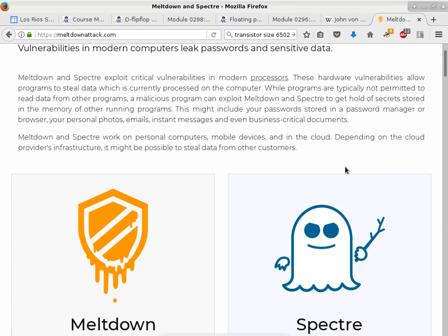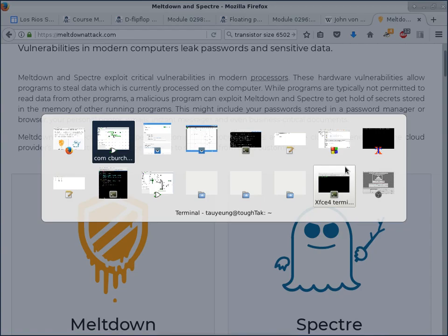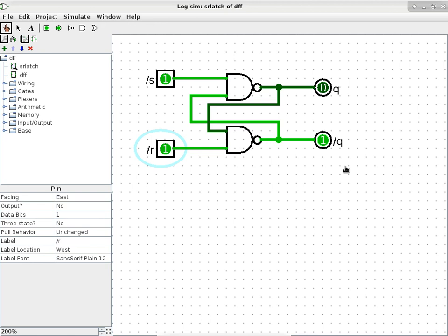So the relevancy of mentioning this has to do with the circuitry that we just analyzed. Okay, this one here, depending on the relative latency between these two gates, the behavior can change. If they're identical, they oscillate. But if they're not identical to a certain point, it doesn't oscillate anymore. So if you are a hardware engineer, and you design something like this, and you did not take into consideration that this circuit may get into a state that it will start to oscillate, and just because of pure luck, the first time you fabricate this onto an actual processor, the gates are completely asymmetric to the point where it doesn't oscillate. So now the asymmetric nature of your actual silicon implementation is masking the issue. The issue is still there, but it's being masked.